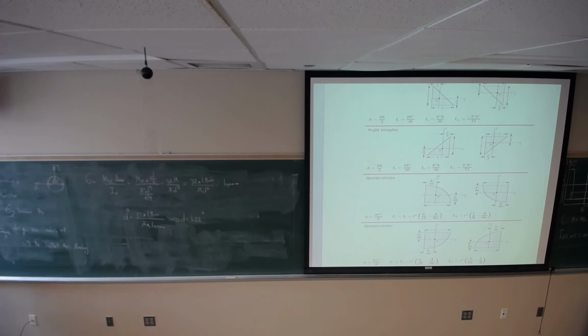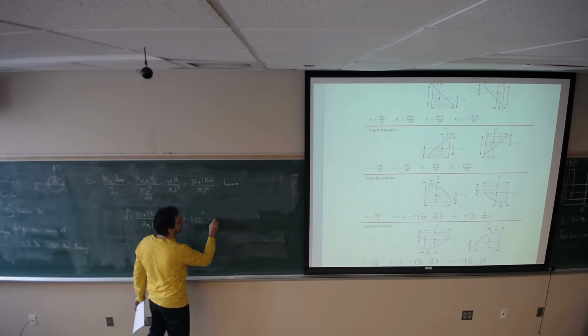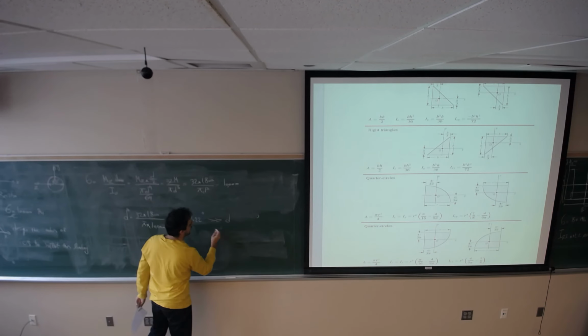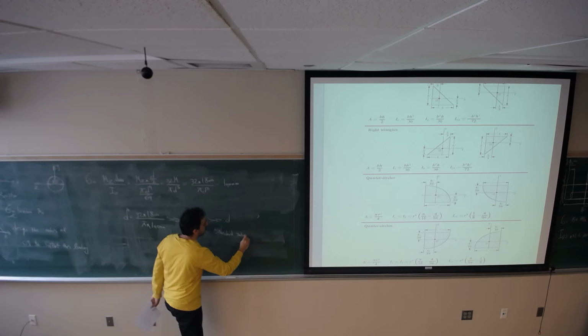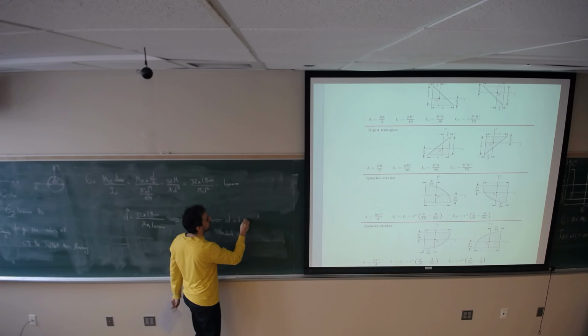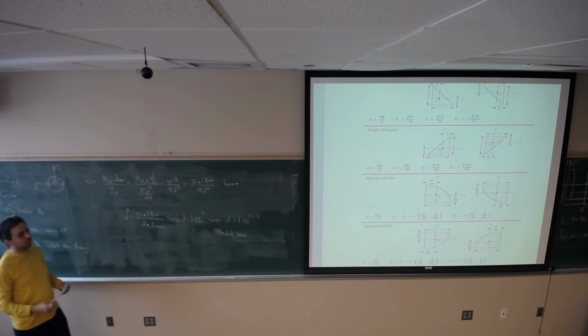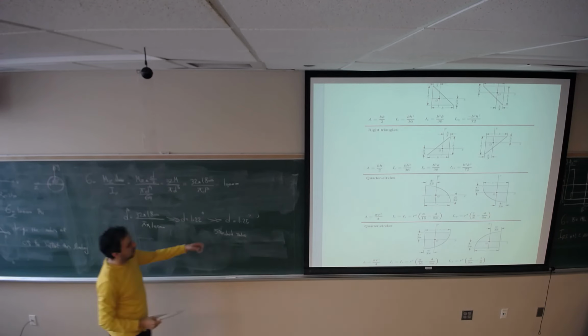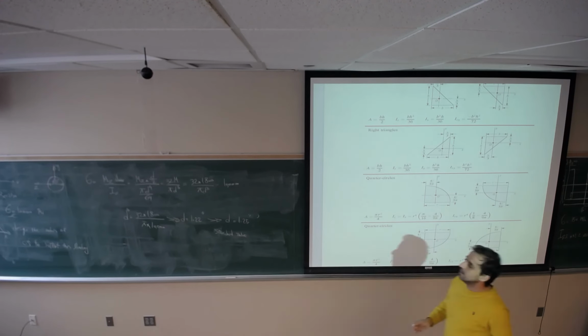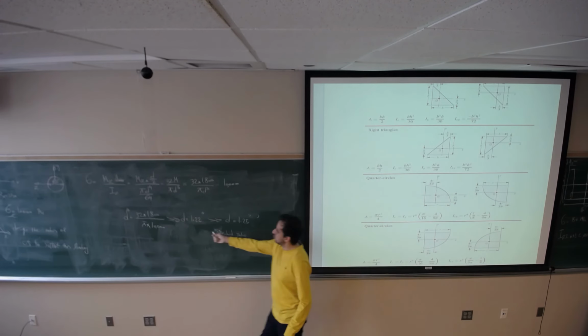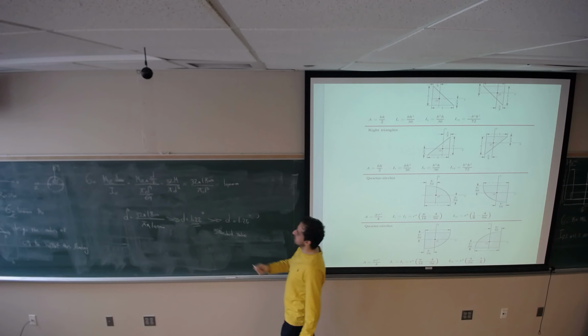If you want to use the standard value by looking at the table, the closest value is 1.25 inch, so we can round it to 1.25. If you want to order the beam, order it with the diameter of 1.25. Although the calculation shows 1.22, this one exists in the market.